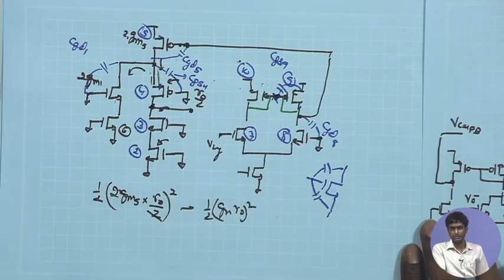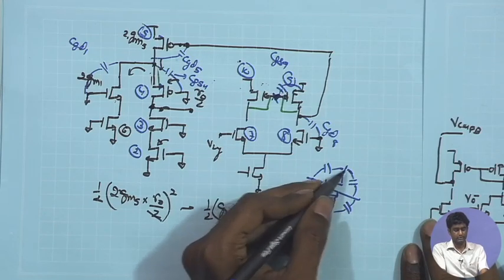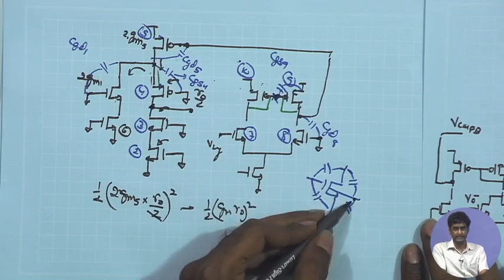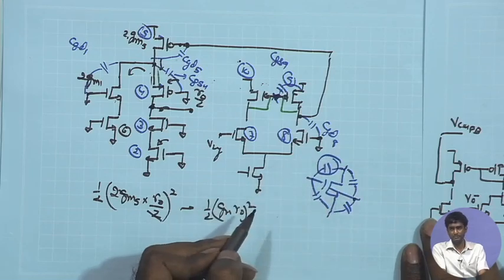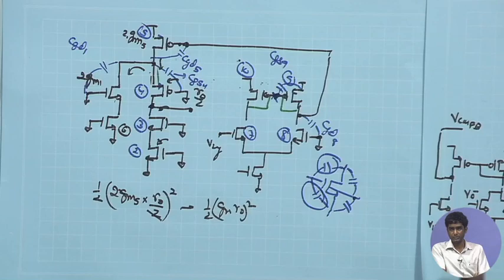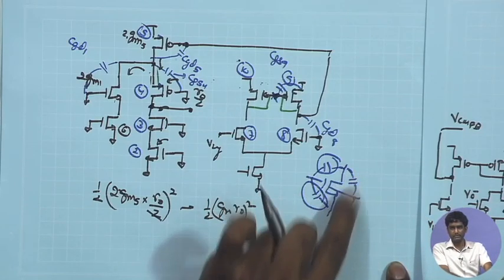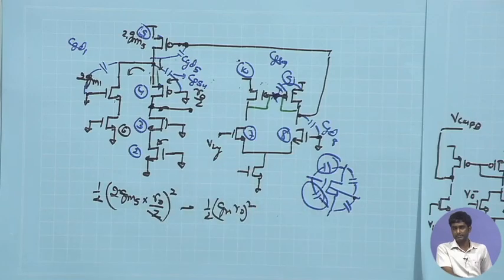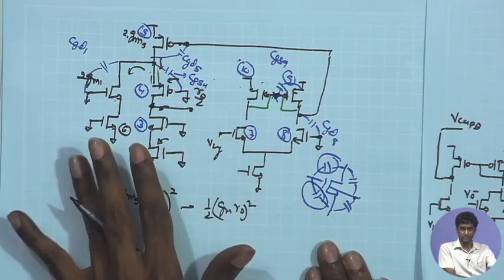The junction capacitance can be relatively smaller, that you see between the CDB and CSB, and moreover they don't undergo Miller multiplication as such. CGS is the largest one in magnitude, so it is important to consider this. These two can be smaller than even the CGD, therefore, I am not considering those two. In order to complete this, we will again come back and complete this discussion.